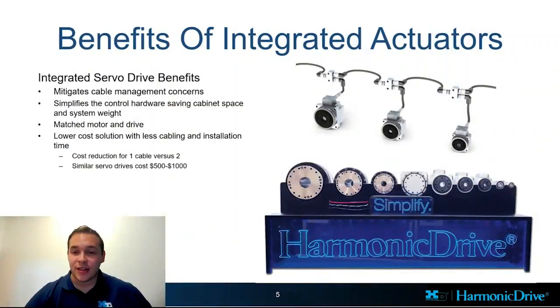Now that I've discussed the trends in the robotics industry, I wanted to touch upon the benefits of integrated actuators. When you have an integrated actuator, you have a BLDC driver right at the source of motion. So you reduce any propagation delays in your cabling, and you simplify the cabling out of the integrated actuator by having either power or communications, or power and communications for CANopen variants. And instead of having to buy an external driver, you can just buy the whole package inside of the actuator, which really allows you to save space in your cabinet.